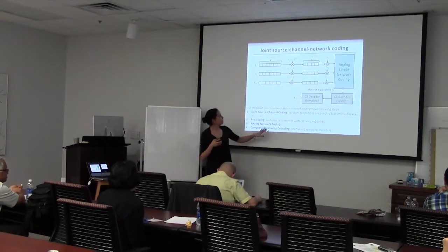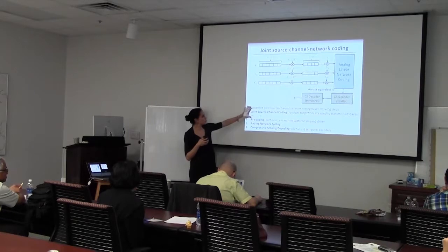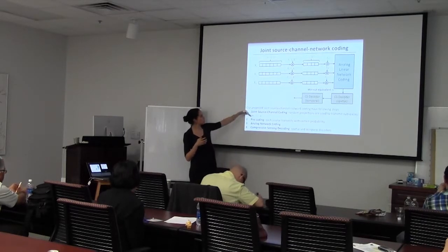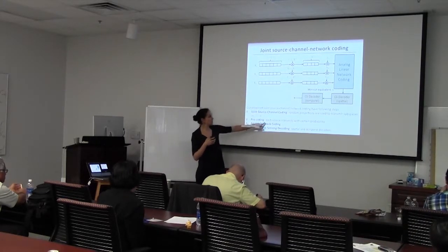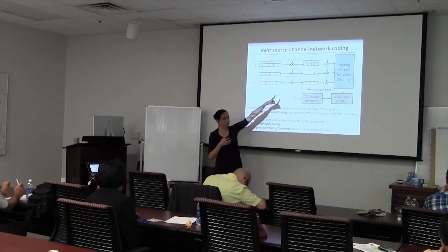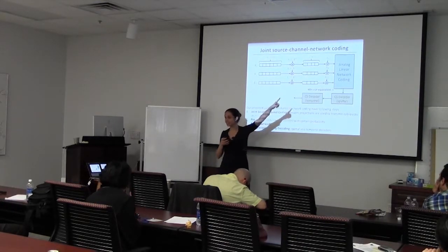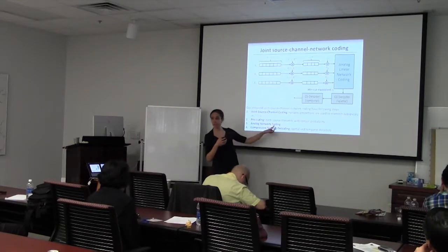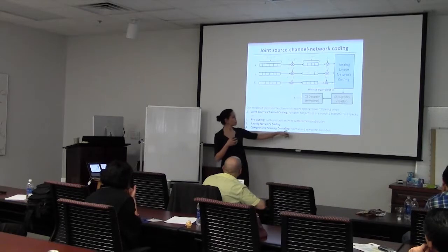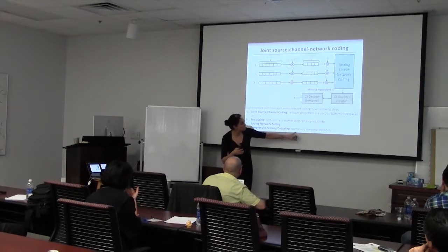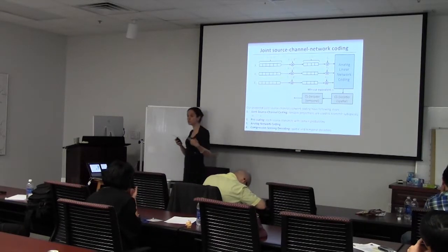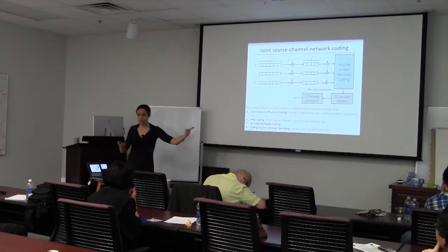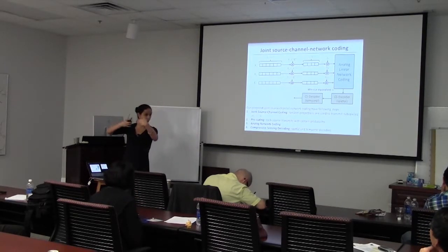Okay? So I have the joint source channel coding. I'm using random projections to transmit subspaces. I'm going to do my really fancy pre-coding, which is turning off sources. That really sophisticated kind of pre-coding. Then inside the network, I'm going to do the analog network coding, which is, again, just amplify and forward. And then I'm going to do compressive sensing decoding, taking into account both the spatial and temporal decoders, like I did with Slepian-Wolf. So that's why we were building it up, where we're just sticking the whole thing together.